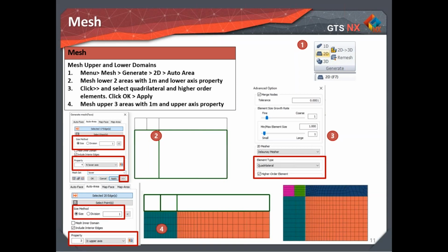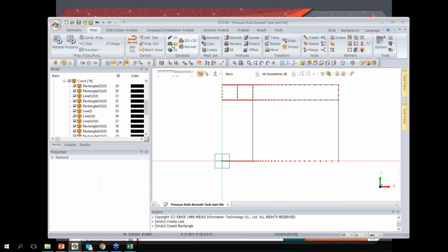And that's good for slope stability, and it's good for cases when you have a high displacement or high deformation mesh requirement, like consolidation perhaps. Like if you expect a high deformation, you can help the program out by giving them some extra nodes. It's one way to think about it. So we can proceed now to mesh.